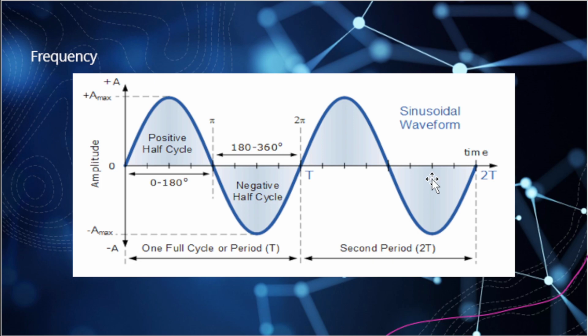What that means is, if my measurement device could only measure up to 1 kHz, but my signal is 2 kHz, my measurement device cannot see that signal. If my measurement device can measure a 1 kHz signal only up to 2 volts, and that signal is greater than 2 volts, well, then again, I wouldn't be able to use that device to make an accurate measurement.